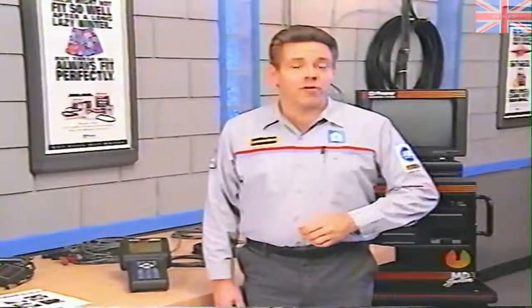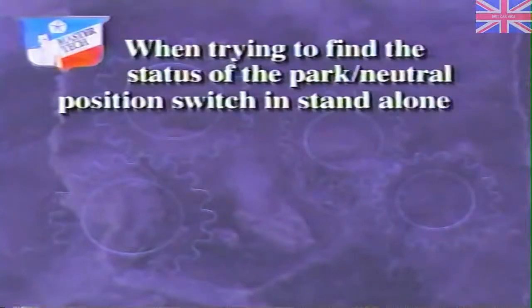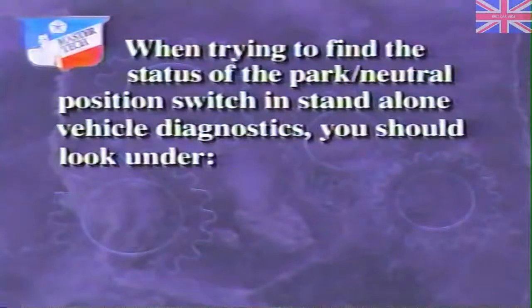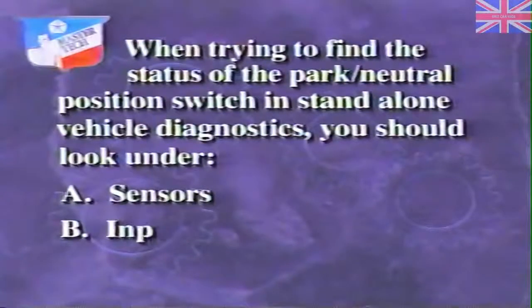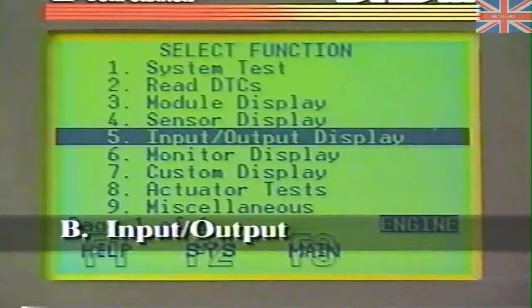Now that you know where to find information when performing vehicle diagnostics, let's take a look at some new features that will make the DRB3 easier to use. But first, try this review question. When trying to find the status of a park neutral position switch in standalone vehicle diagnostics, you should look under A, Sensors, B, Input-Output, or C, OBD2 monitors. The answer is B. Since the status of the park neutral position switch is either park neutral or drive reverse, you would find it under Input-Output.